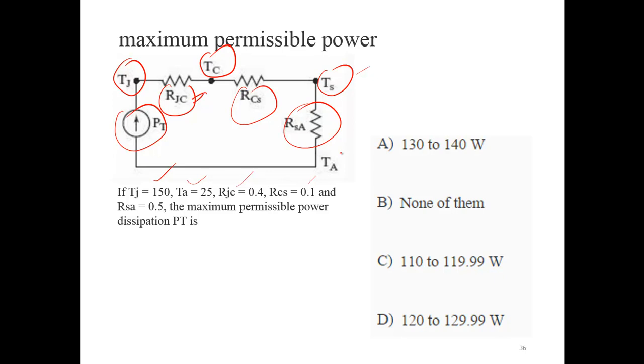Think about it. If you have a 1000 amp device, a current through either a transistor or diode or whatever, and the drop across it is 1 volt, you know 1 volt is not much, but it's a kilowatt. You have to dissipate 1 kilowatt in that device.